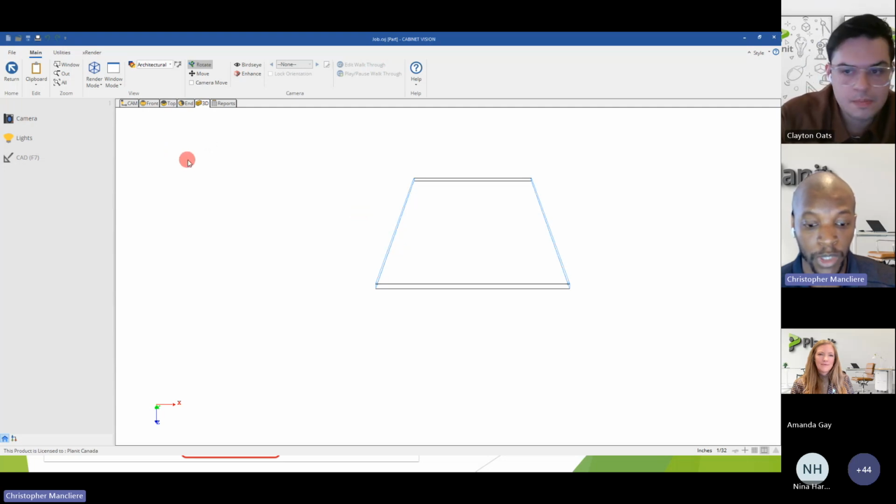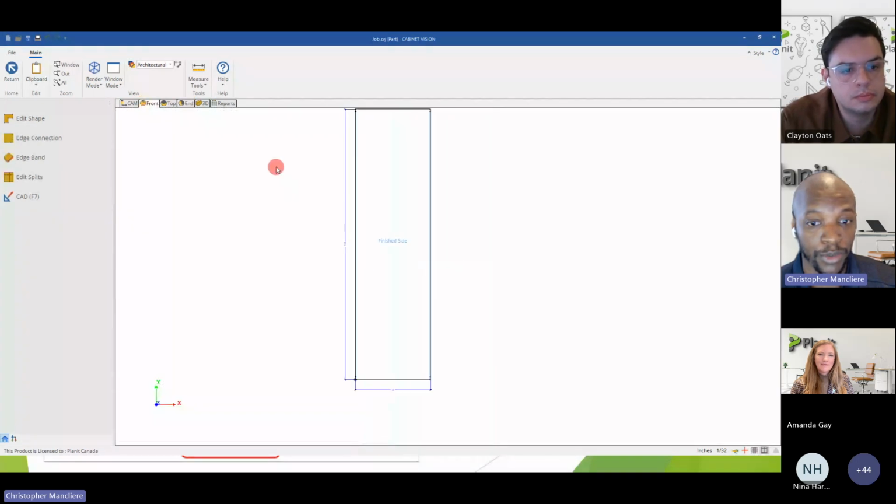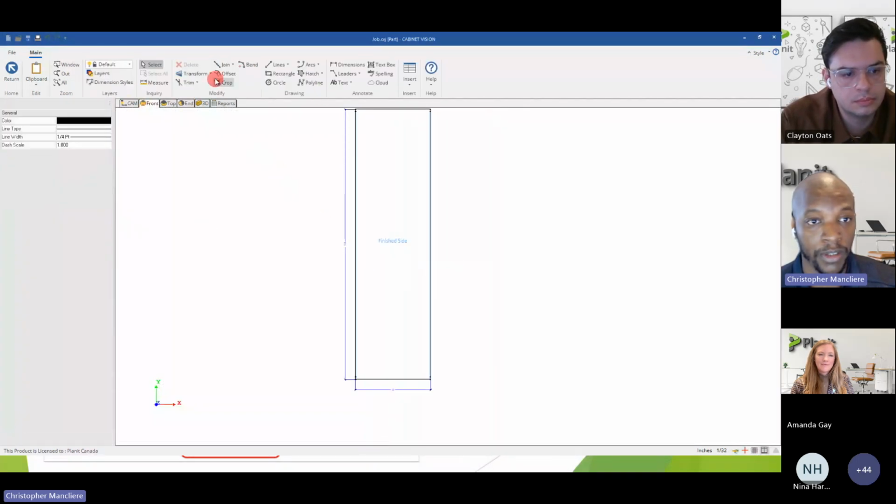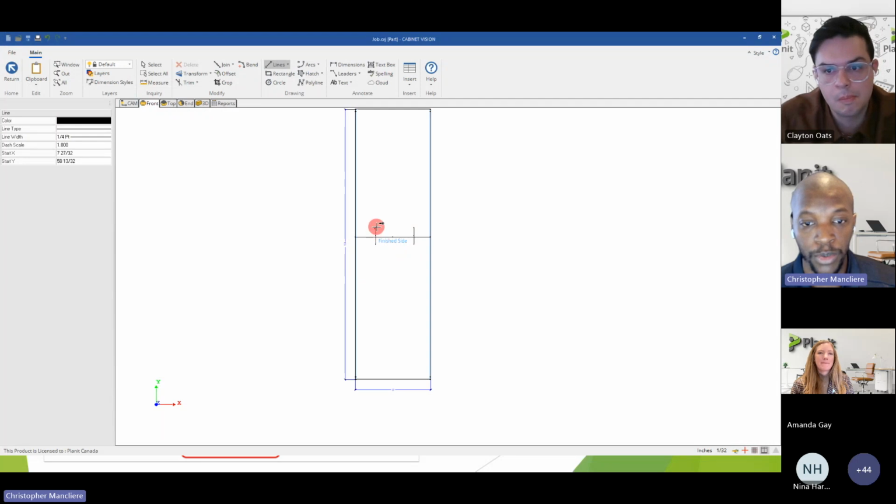So I will be able to fit them on the side of the cabinet and still have the tenon to assemble my cabinet. The only thing you're not going to have, and just to keep in mind, is calibration is not going to create the machining to get those two pieces together. So you might have to manually create a lamello or something just to get those together. But the machining on the side will be created on part A, and it will also be created on part B on both ends for you. You're just missing this little part that calibration will not do automatically for you here.